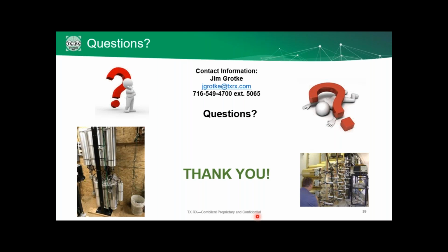Jim, here's another question. Do you consider space requirements at the sites? We will consider space requirements if the customer provides them. If they have specific considerations, we'll do our best to meet that. But space quite often depends on the frequency plan provided to us: separation of transmit to receive frequencies, number of channels, number of antennas provided, and antenna separation.